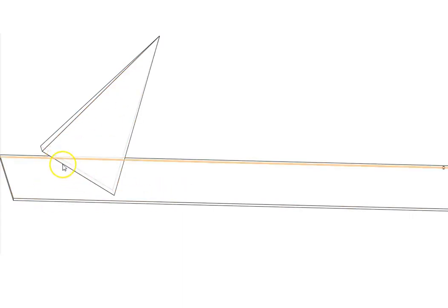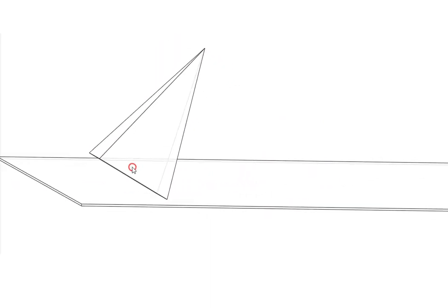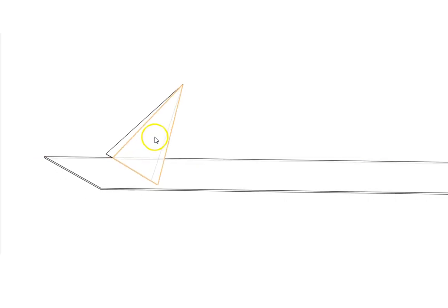Both are the same, in fact, since the axis and the base are perpendicular. So if the base is tilted at 30 degrees, naturally the axis has to be at an angle of 60 degrees. This is something which you have to be aware of while doing projections of solids. And with that introduction, I think we'll also see how we could actually represent this in 2D.